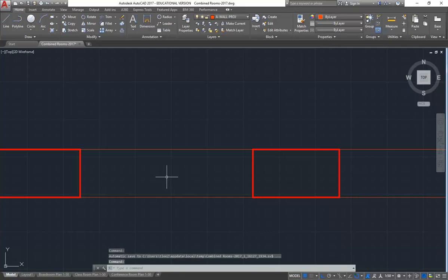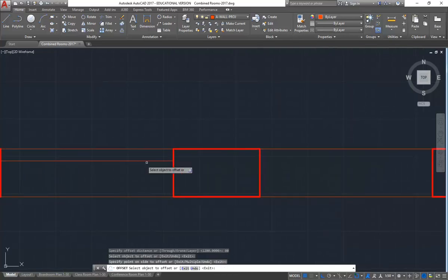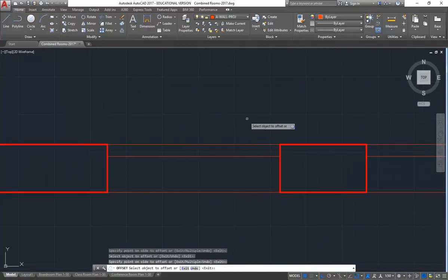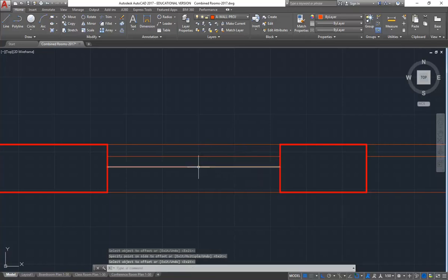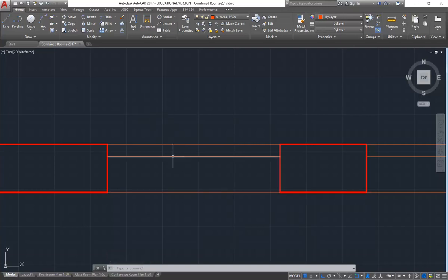And then I'm going to offset, I'm just guessing, 80 mil. So using offset, I'm going to make it 80 and then come down and do that on both sides. And then I'll offset 70 mil from that line again. No, that looks too small. I'm just trying to scale it by eye off these drawings. That's too small. I'll tell you what, I'm just going to do it the size I would do it, which is 50. So I'm going to make this 100.